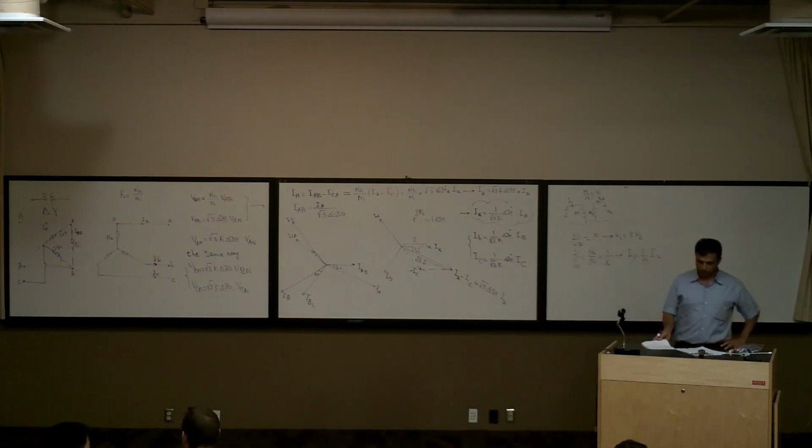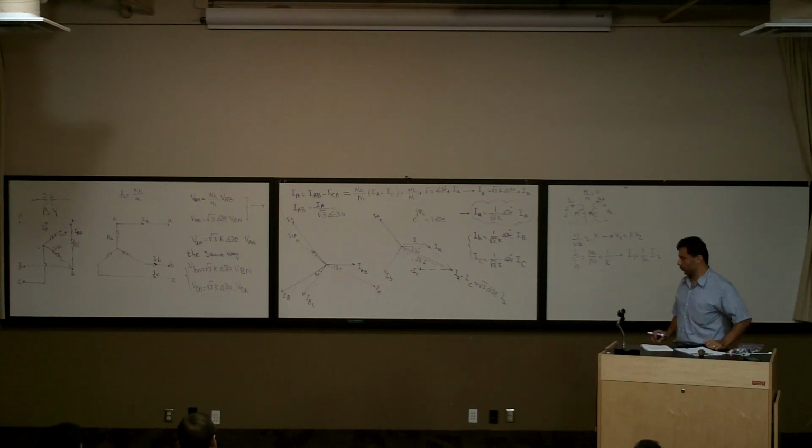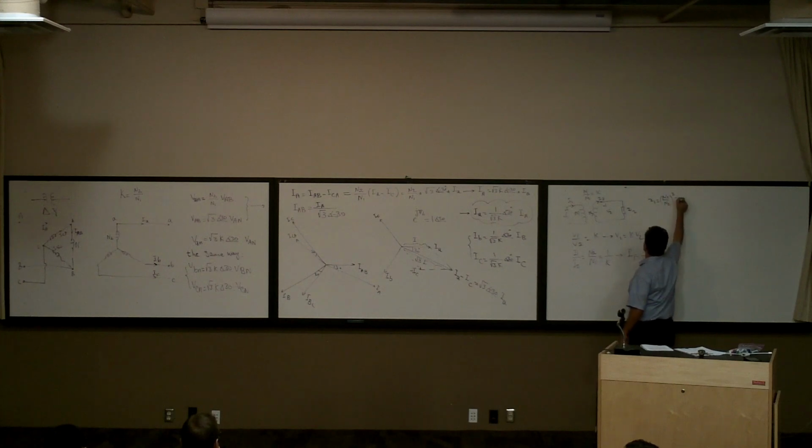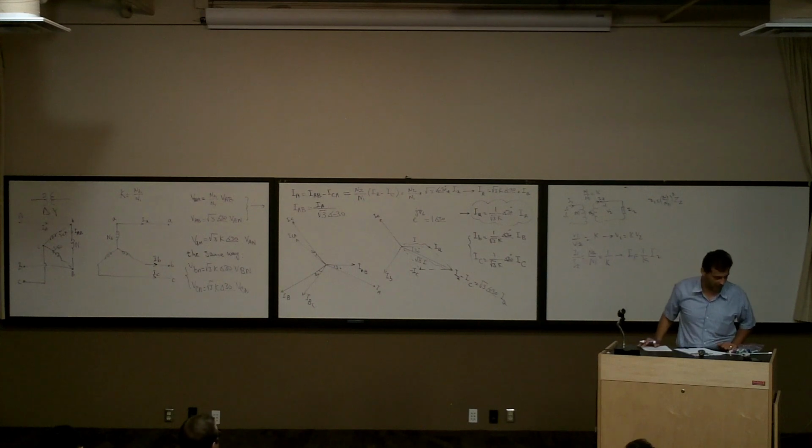Now we know how to convert the voltage and current from the primary and secondary. How about the impedance transfer? We want to see if you have something in the secondary, if you are going to bring it to the primary. Here was easy. If I had for example, impedance here. If I want to bring it here, we said, okay, if this is a Z, here, Z2, let's call it Z2. Z1 is going to be N1 over N2 to the power of 2, Z2. That was how we did it for the single phase transformer.